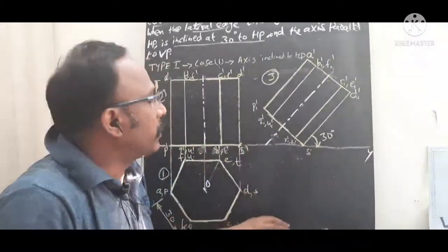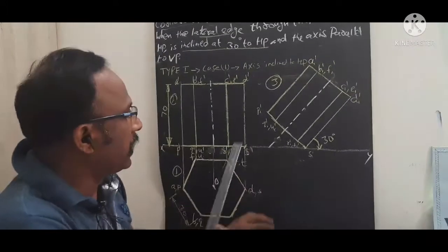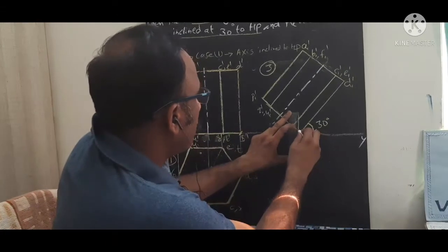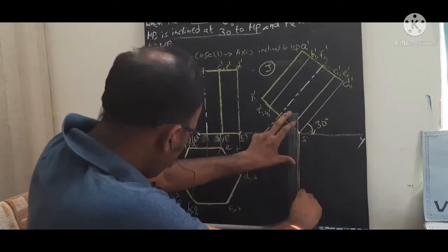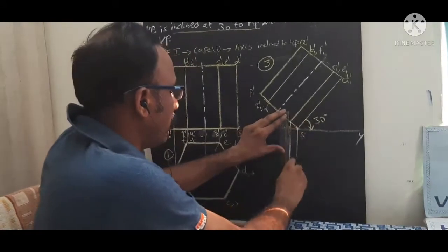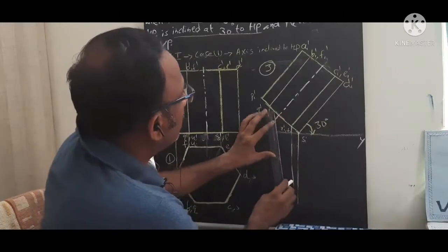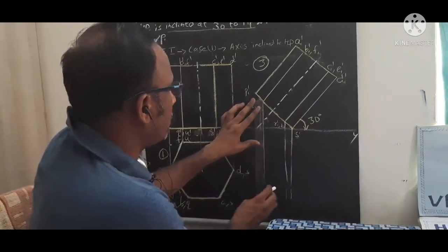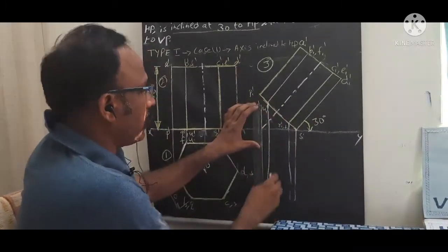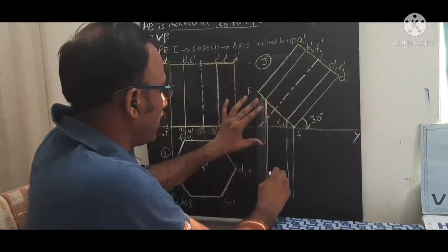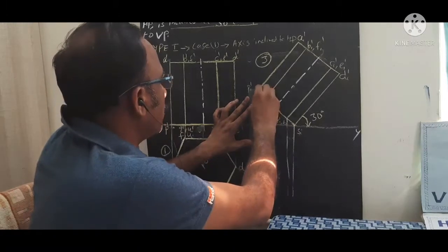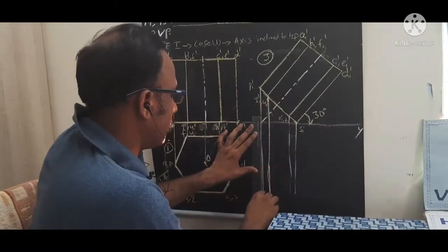Now we are going to complete the last step, for which draw the vertical line and horizontal line. So draw the vertical line from the bottom hexagon first. You need to draw this vertical line from all these points. Here no need to draw from the center line. Center line is not needed. No need to draw the vertical line from the center, right? Only from base corner edges we need to draw this vertical line like this.